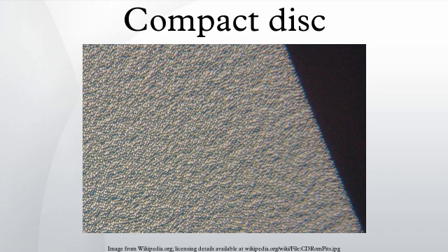Speed. Due to technical limitations, the original rewritable CD could be written no faster than 4x speed. High-speed rewritable CD has a different design that permits writing at speeds ranging from 4x to 12x. Original CD-RW drives can only write to original rewritable CDs. High-speed CD-RW drives can typically write to both original rewritable CDs and high-speed rewritable CDs. Both types of CD-RW discs can be read in most CD drives. Higher-speed CD-RW discs, Ultra Speed and Ultra Speed Plus, are now available.